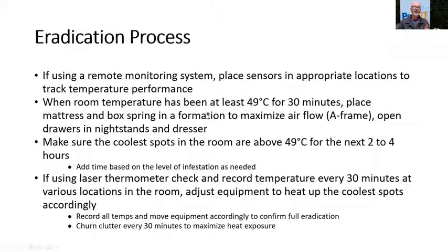Then you could start your timer, be it 2 to 4 hours, depending on the severity of the treatment process. Using simple devices, it could be a thermal imaging camera or a little digital thermometer, or we've got some more sophisticated thermocouple systems that you can use to monitor and also to do some reporting. And you can do that from outside of the room.